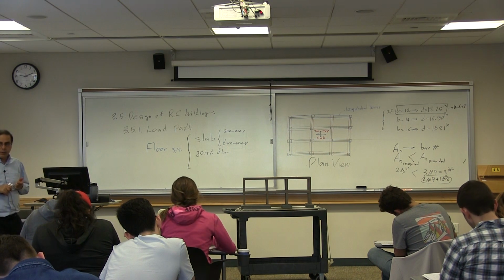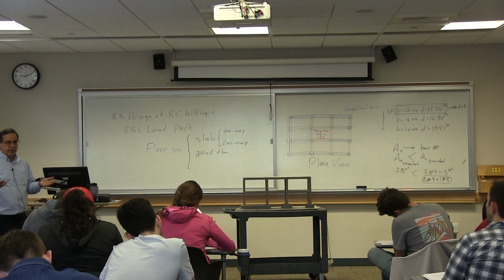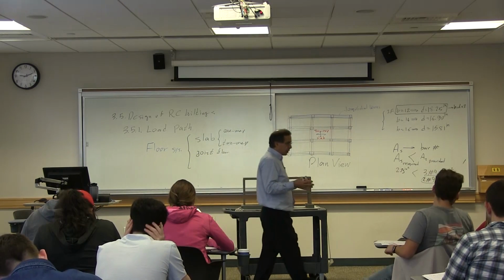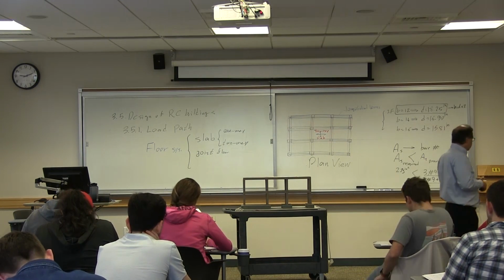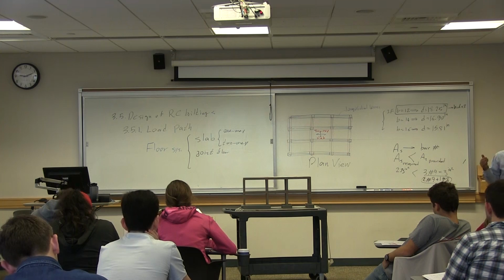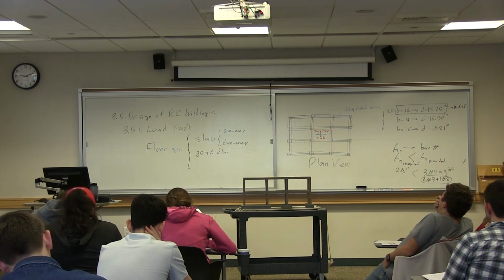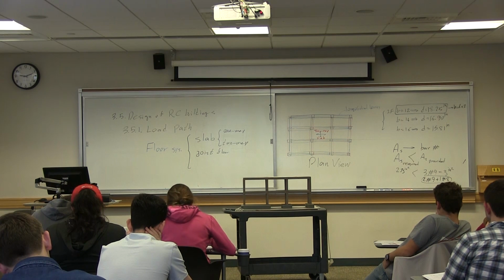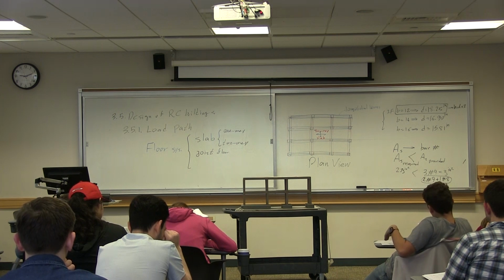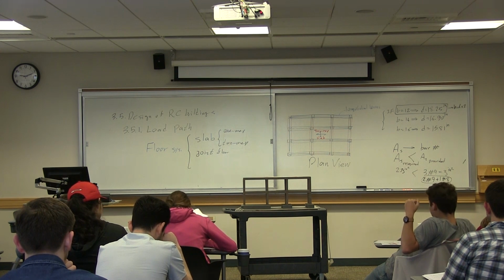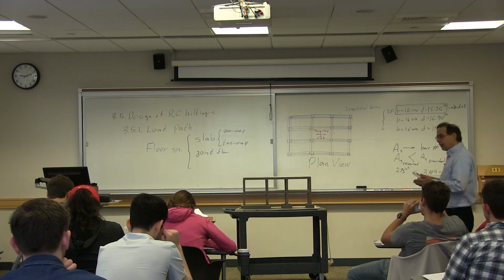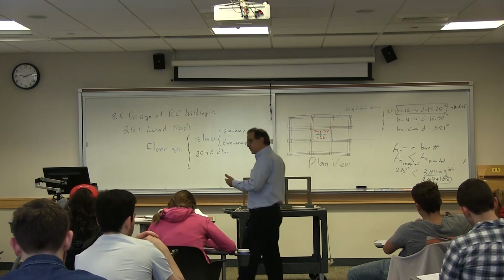In general, all slabs are two-way. That means regardless of how long in one direction or short in the other direction, the loads will be transferred to both beams. However, from an engineering point of view, if a lot of load is transferred only in one direction and only a small portion of the load is transferred in the other direction, we call that slab one-way slab. So what is a one-way slab? When a lot of load is transferred in one direction.